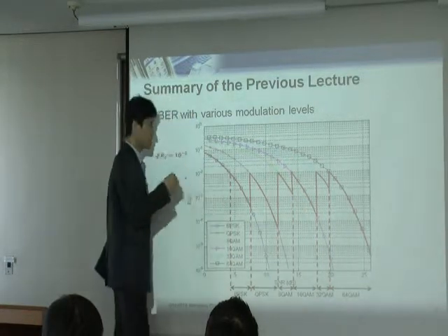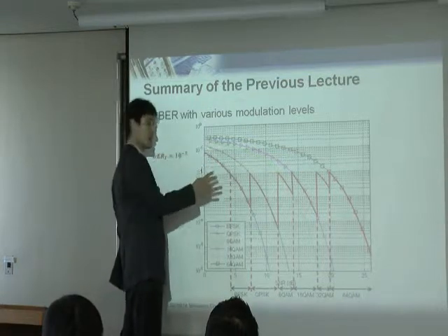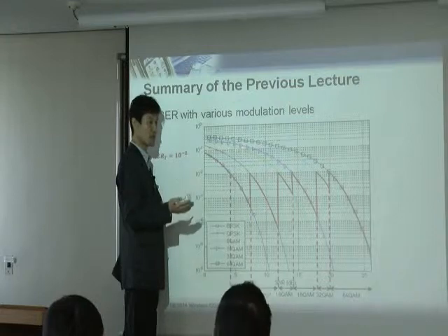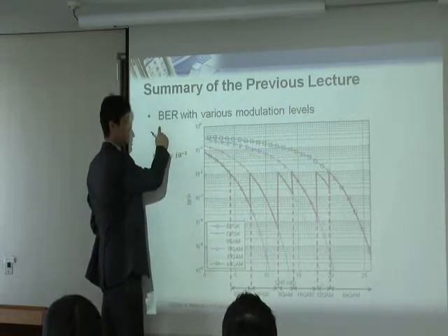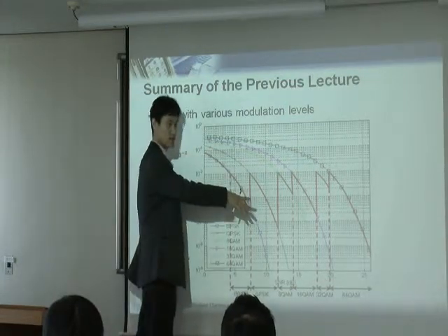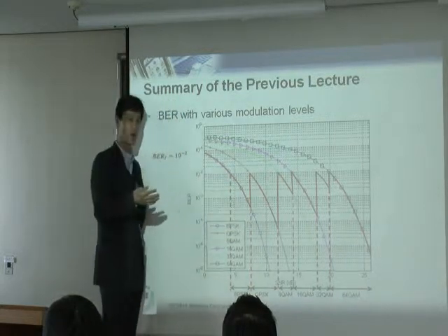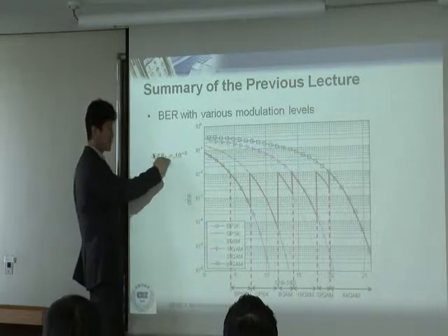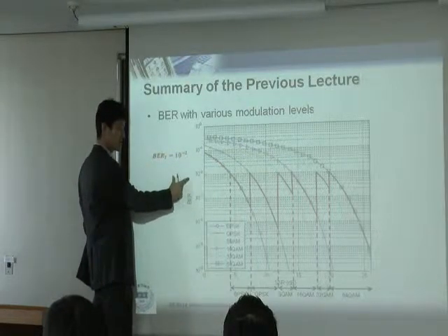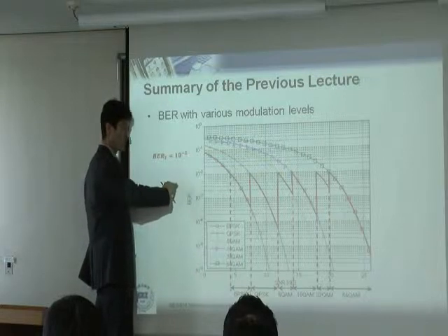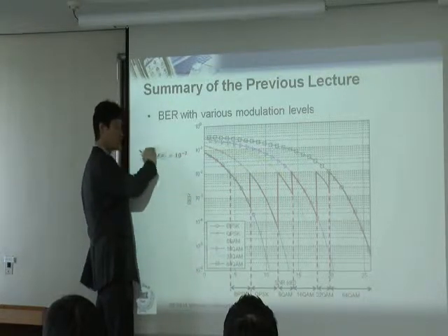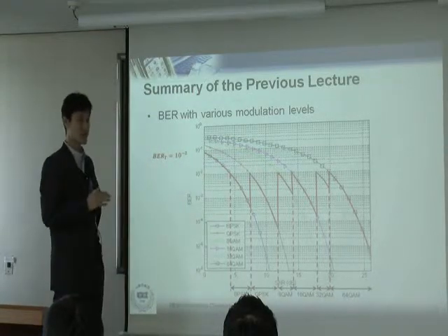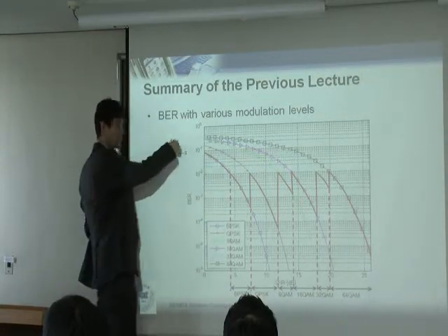But the thing is that, think about it this way. The channel is changing every time. We typically assume a quasi-static channel, which means that our channel is like a staircase function. During a certain duration, we just assume that the channel is constant. And on the next symbol transmission, we make another constant, but that value and the previous value can be different. So like a square case. But the actual channel is not like that, right? The actual channel is constantly changing.